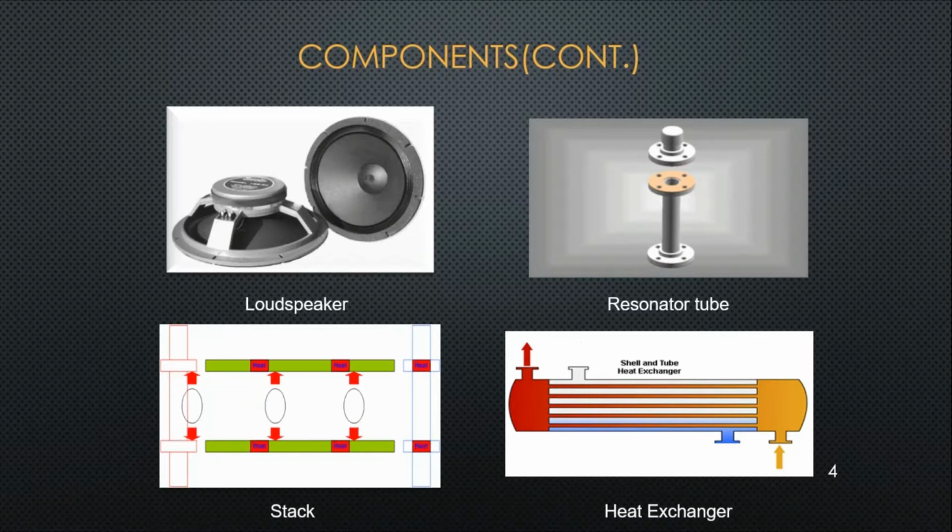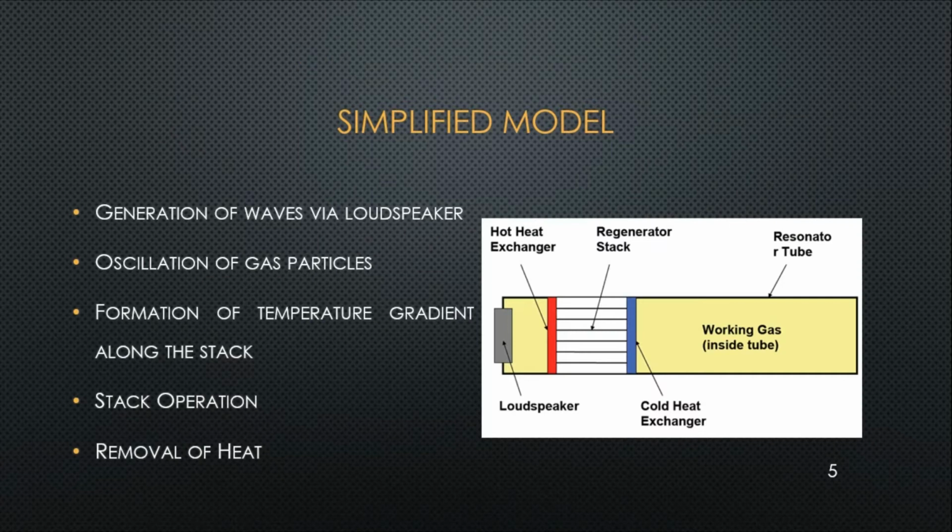And this is the cool spot of the thermoacoustic refrigerator. From the hot side we will maybe attach an aluminium plug or something like that so that the heat continually escapes. This is the simplified model of a standing wave thermoacoustic refrigerator. Firstly, we want to produce the sound from one end, and the other end will be closed. In the case of the standing wave thermoacoustic refrigerators, that is half wavelength.